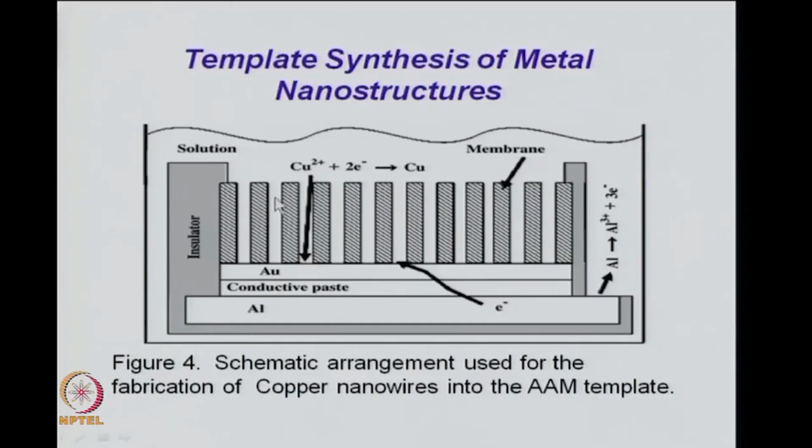So, wherever copper 2 ions are there, they get reduced and they form copper metal layers in these cavities. So, now you have a particular order of copper metal which are separated from each other by this gap, because no copper metal can deposit here, which are the membranes, and only the gap which is available where the solution can go can be reduced to copper metal.